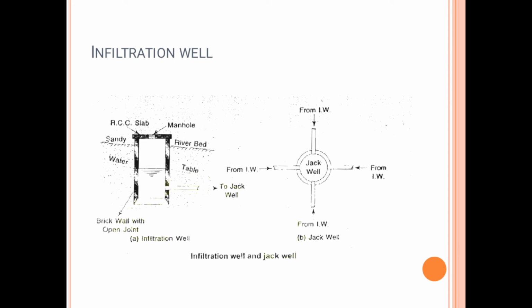This is the infiltration well diagram. Normally the wall is constructed with the help of RCC or brick masonry. Then open joints are provided. Through these open joints, water enters into the sump well.